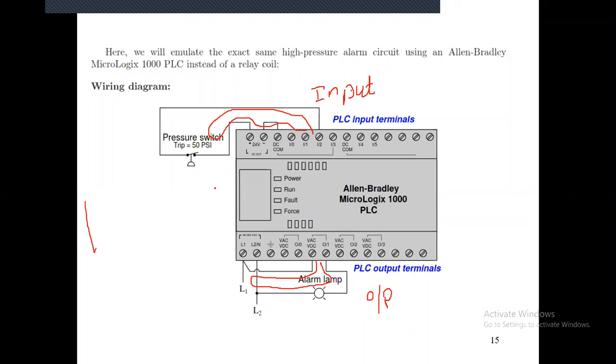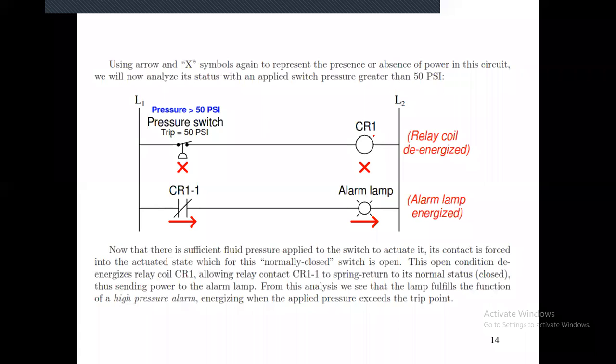We have a power rail here, and then we have this overload switch, and then we have the relay coil, which is contacted, and then we have this lamp. So this was the relay, and this is the lamp. Okay, right? Here you see this one is the input loop, and this one is the second loop, and here they are actually separated, right?